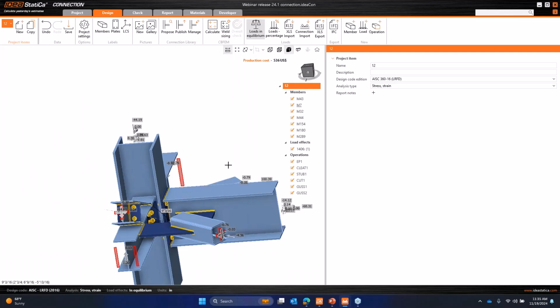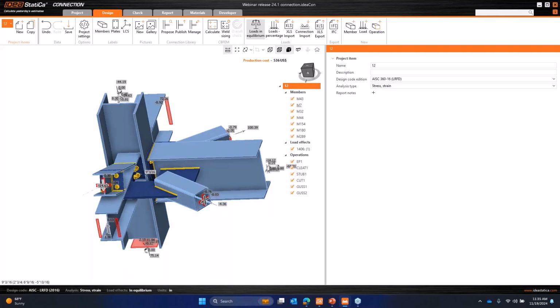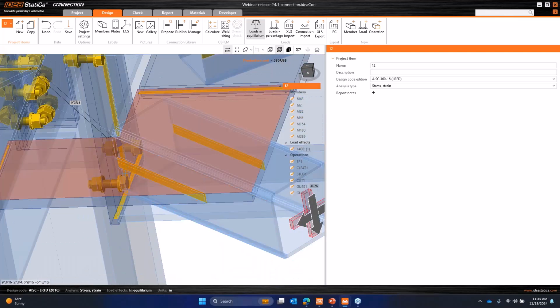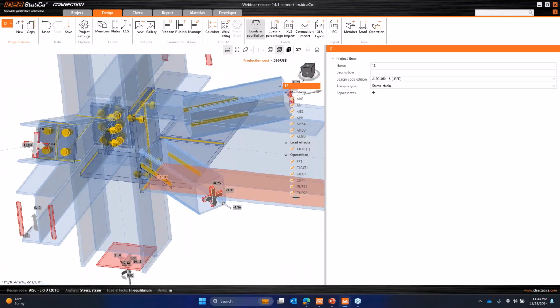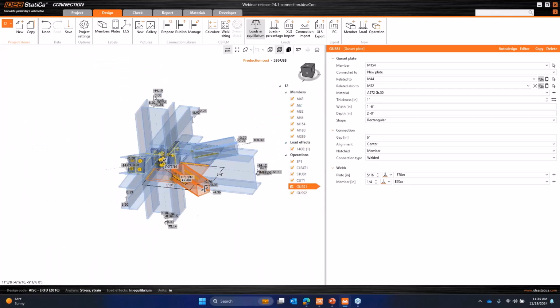You can also look into some of the complete weld lengths that can help you. You will not be able to directly look at the weld lengths, but you can direct yourself with some cut operations. In this case, if we want to see this notch on the member for the length, we can look at one corner to the other corner and measure that length. This will be very useful whenever you're working with your operations and you're looking into putting some dimensions. You can easily measure these changes and input those values into your operations.